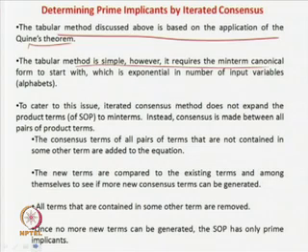So, in today's class we will see another scheme of doing the same thing, but here we will not take a canonical form, or here we will not blow up the function and then bring it down. If you look at the Quine's method or the tabular method, what we have done is we have taken a function and made it into a canonical form. Canonical form means you are opening up the function, and then you are trying to merge terms which have consensus, and finally we land up in a situation where no more terms can be merged. So, we get the set of prime implicants for the function. But the main thing was that it was exponential, so we had a problem.